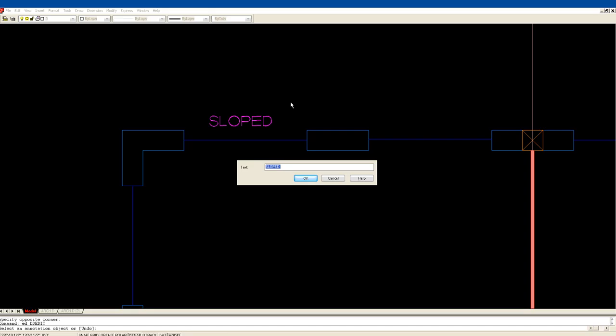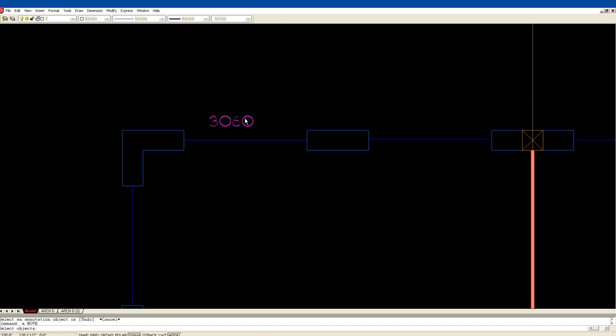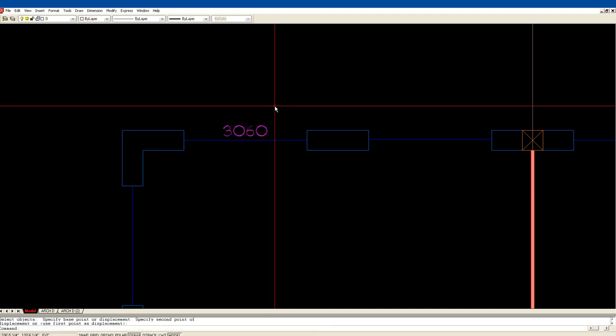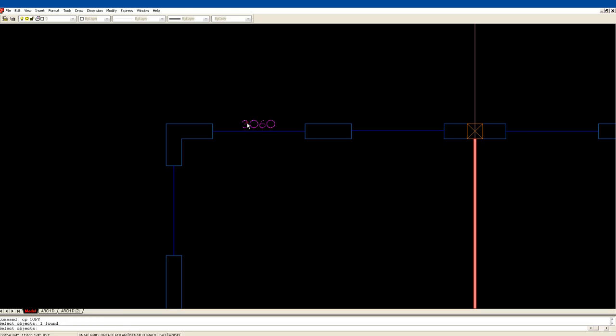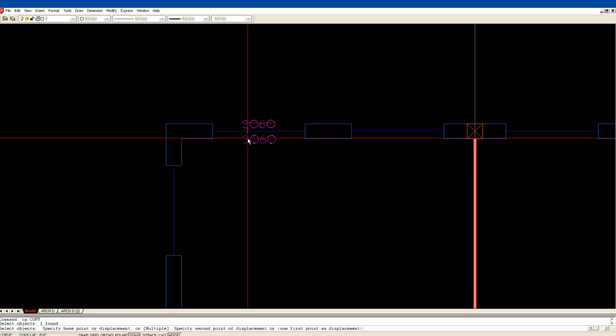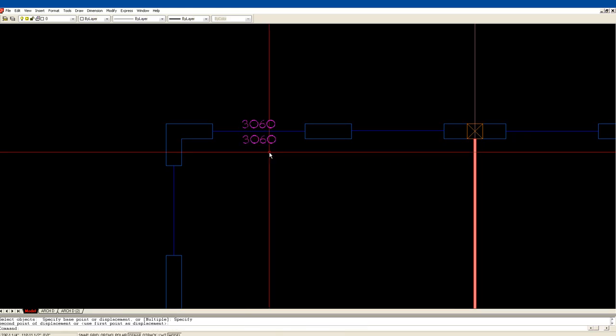Okay, so these are 3-foot windows. I'm going to make them 6 feet tall. Okay, and so I'm going to change this to 3060. Okay, 3060. Feet 0 inches by 6 foot 0 inches. And you just hope that they've got a professional framer who doesn't read that as 30 inches by 50 inches.